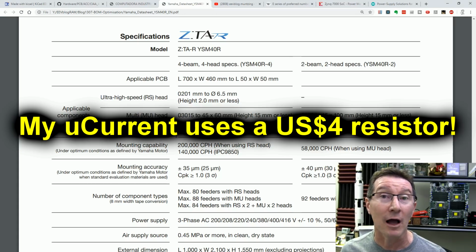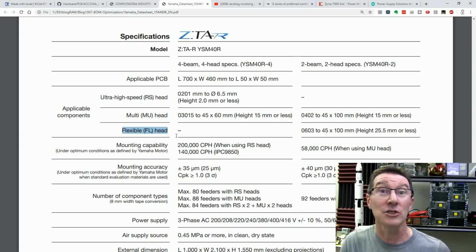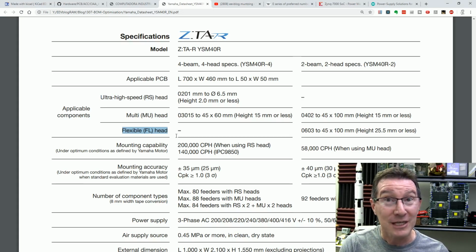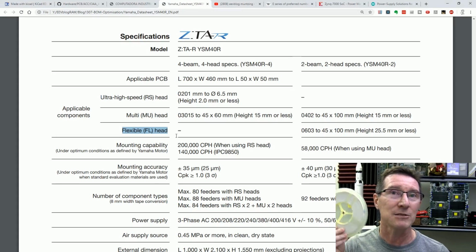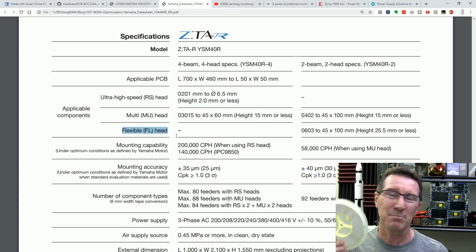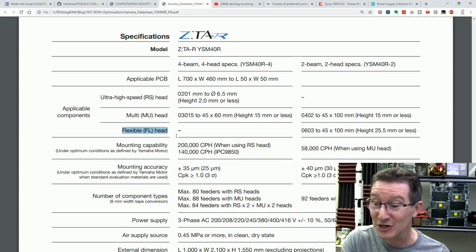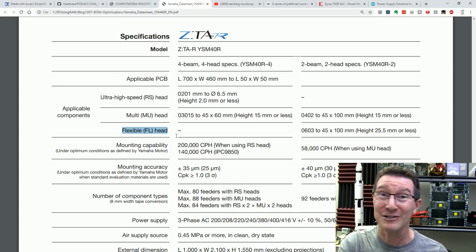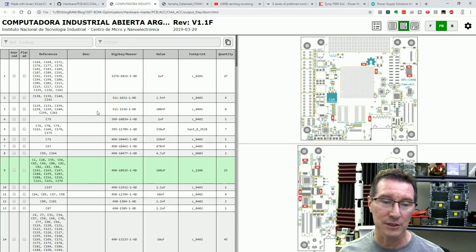You can pay $1 for a really good high precision low tempco resistor, for example. So if you choose a real ultra tiny one and there's 5-10% wastage, that's going to add up to your assembly costs. So they might say, okay, we need 3,000 of these parts, but give us a reel of 4,000 because we're going to waste a lot of them. And there's a waste bin on the pick and place machine where all these fallen components just drop off and fall into.